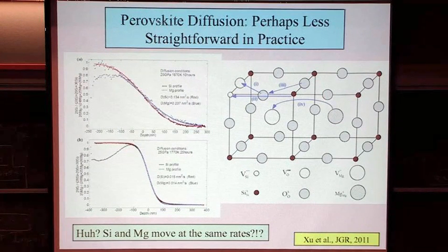the thing that would simplify things the most would not be calcium. It would actually be trivalent iron. Because trivalent iron would in turn generate vacancies galore in the sample because it would not necessarily be a charge balance substitution. So I would actually prefer not to have an isovalent substitution. I would prefer to have a non-isovalent substitution. By all means, stick aluminum in here, put trivalent iron in here.